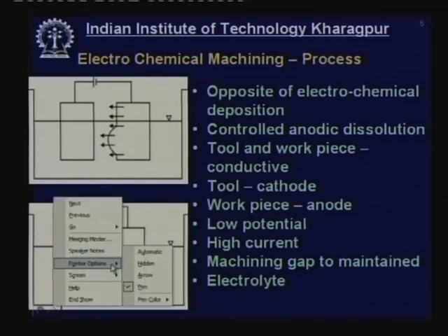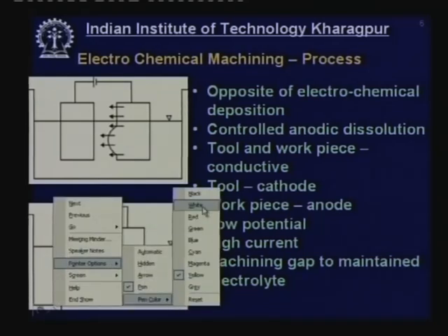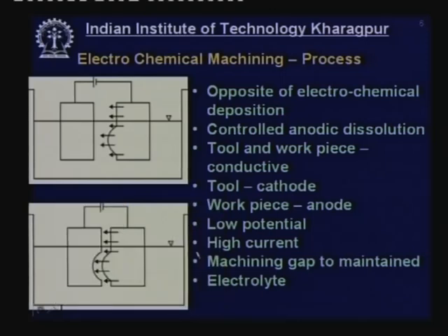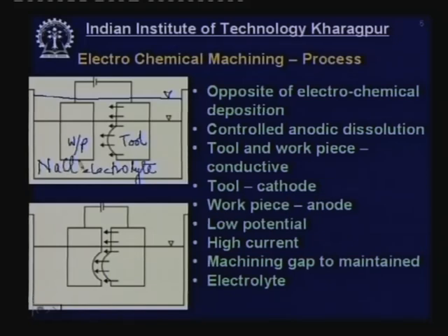In the electrochemical machining process, like any other process, we require a workpiece as well as a tool. So, this is my tool and this is my workpiece. They are immersed in a solution just like in electro discharge machining, but this solution is not a dielectric. This solution is an electrolyte. Typically, sodium chloride salt is used to prepare an aqueous solution as the electrolyte.